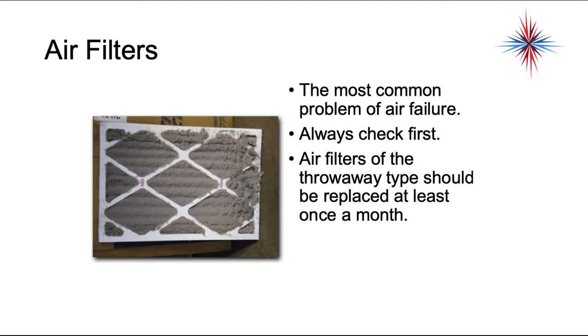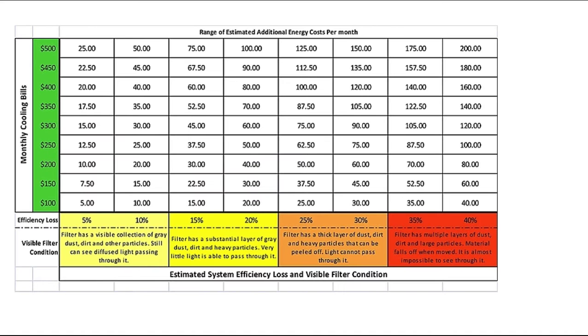But air filters are the throwaway type. People are saying 2-3 months. Some people say 1 month. Look at the situation. However, if it's someone that has pets, or someone that has a dusty house, don't tell them your house is dirty, you need to replace the filters every month, but just suggest that they replace the filters more often.